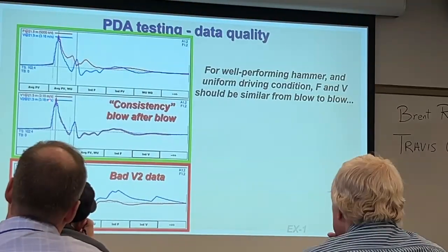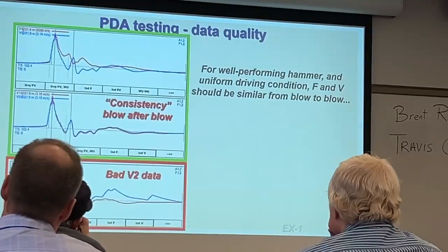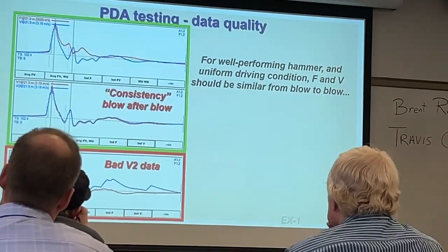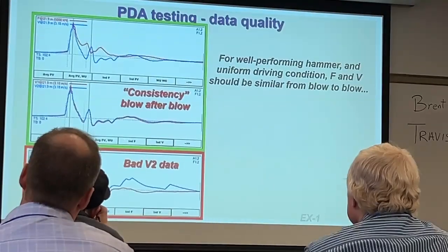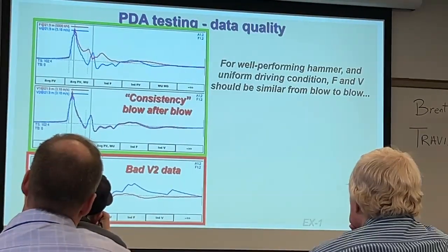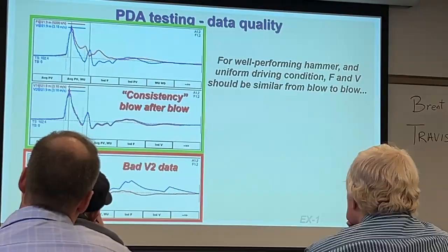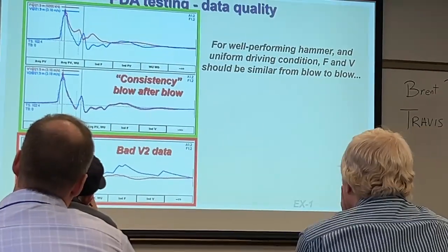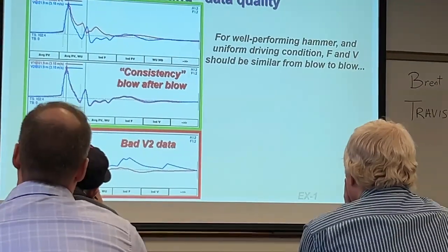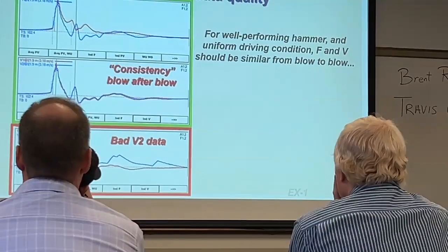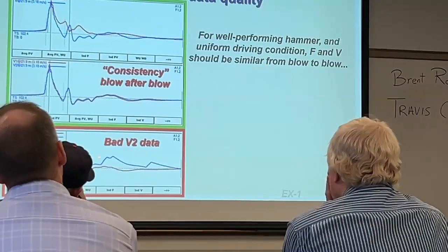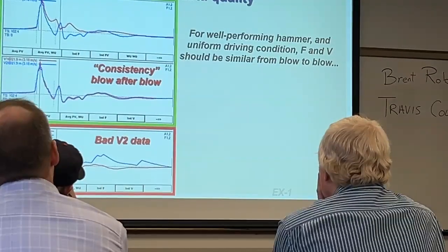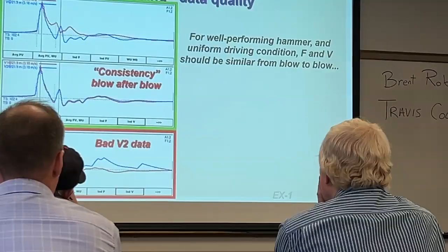If we look at consistent velocities, they're good, but on an adjacent blow, we see that one of the accelerometers caught a spike of noise, and because of that, this accelerometer is not really returning to zero and giving us troubles. What do we do? What can we do with an accelerometer? Disconnect. We can turn it off. And so we can tell it to ignore that data set and just use the one for that single blow, or if it's happening on more than one blow, for others that are going on there.